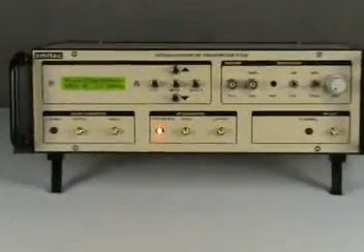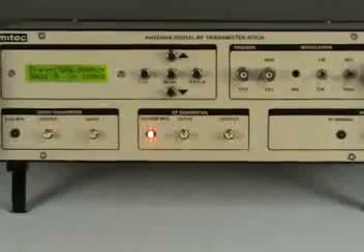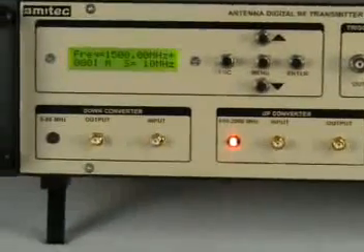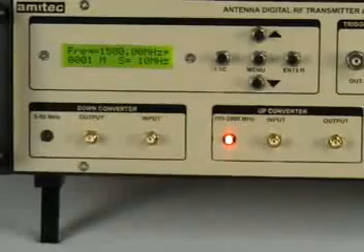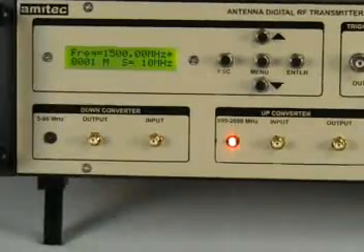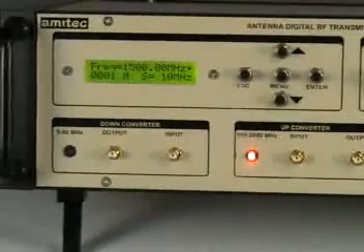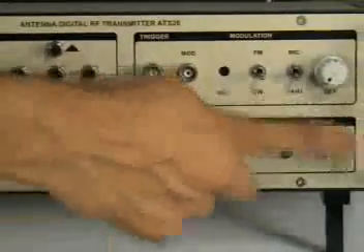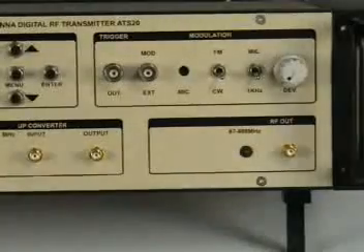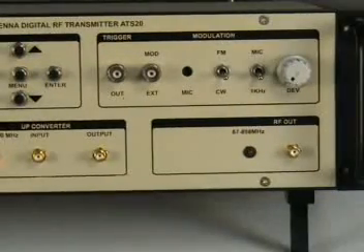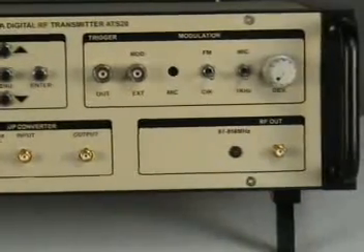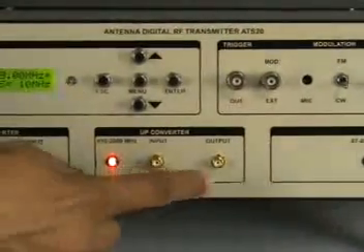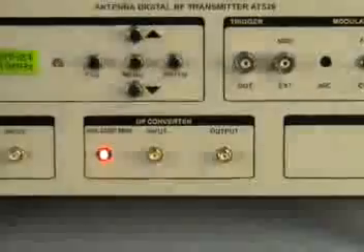The minimum step size available in the PLL synthesized transmitter is 50 kHz and the maximum step size is 100 MHz, which are selectable. The RF output from 87 to 898 MHz is available at this RF output using an SMA connector, and using the up converter, 899 to 2000 MHz output is available in this block.